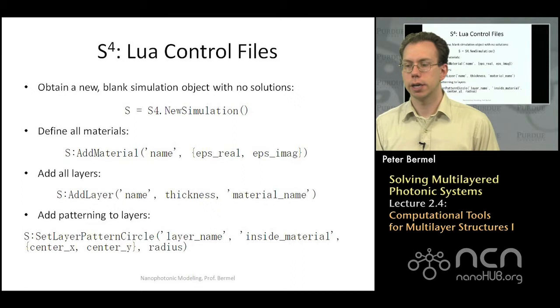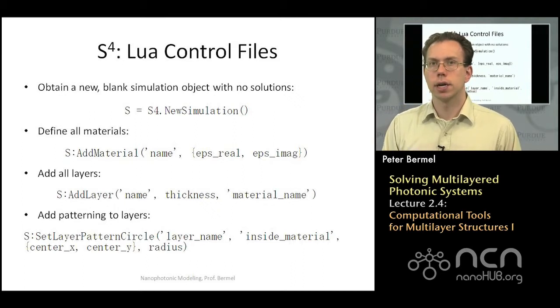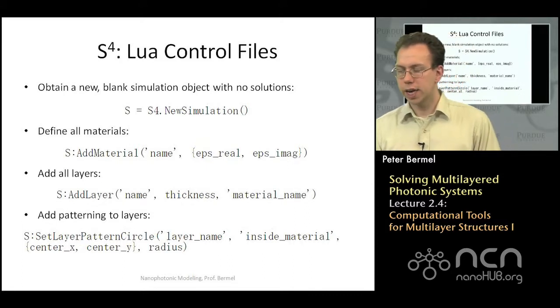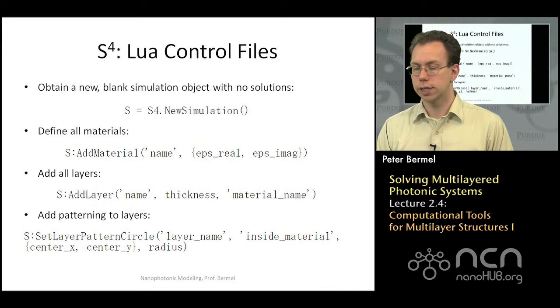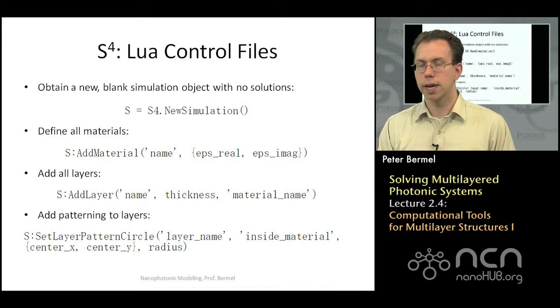So let me walk you through briefly how you would set up a calculation in S4. S4 is based on the Lua scripting language. If you haven't heard of it before, you can think of it as something similar to Python. The idea is that you'll create a new simulation, which you can call any variable you want, which you can just call S, by choosing the member function of the main S4 object, which is called new simulation.